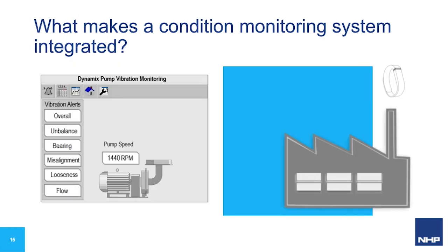And then, of course, we need to monitor. It doesn't make sense that we've got all this data and we don't do anything. So trends and limits are used to monitor the propagation and then severity of faults. And we need to present this in a meaningful, intuitive way, rather than just numbers. The numbers are still there because those are important. They're available to be trended, but presenting this data on your existing SCADA system instantly increases your reliability team by the number of operators with eyes on the SCADA system or people getting alarm notifications.